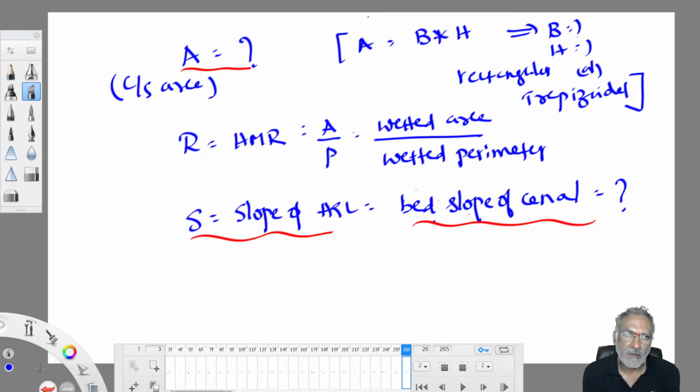The loss of water that evaporates over a period of time is much more than the energy we give in pressure conveyance. Instantly, gravity conveyance is more economical, but we operate this system for a long period till the end of the design period. So over the design period, pressure conveyance is better than gravity conveyance. Therefore, we recommend that the most.